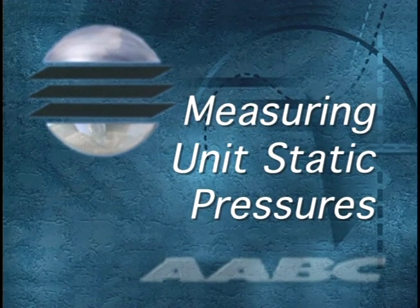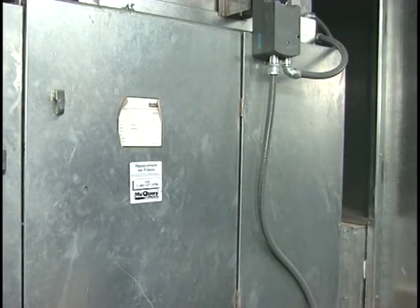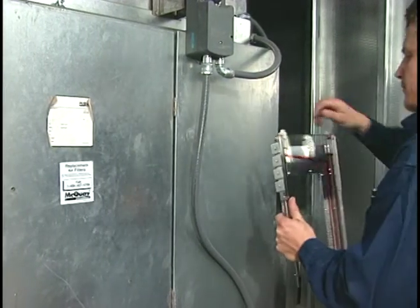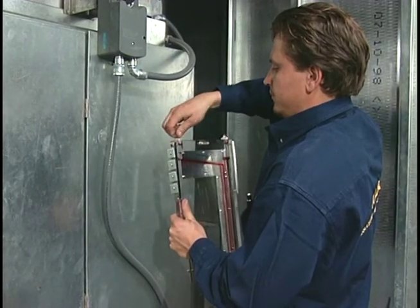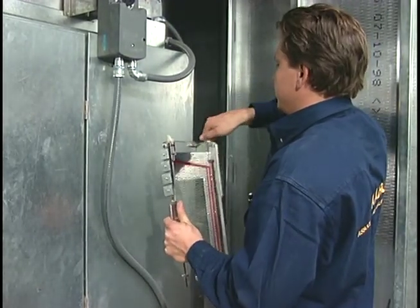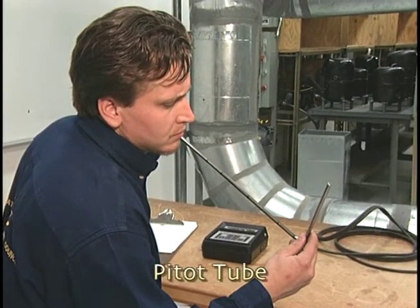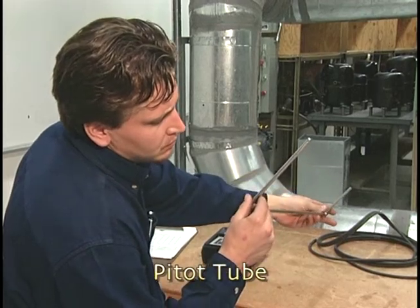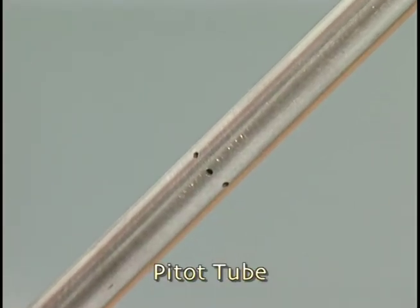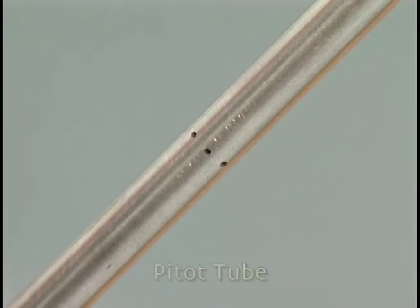Measuring unit static pressures. With the system operating, static pressure readings can be taken in the air handling unit. The technician selects a manometer, pitot tube, and connecting hoses to take the readings. Manometers and pitot tubes are precision instruments that should be handled with care to avoid damage. The pitot tube's impact and static pressure sensing holes should be kept clean and open.